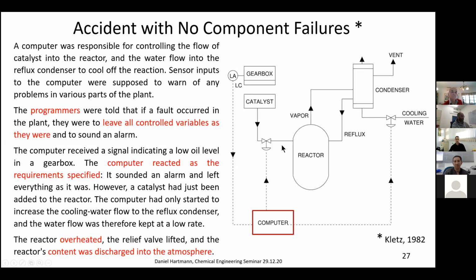And then there was a problem, not related directly to this reactor. The gearbox had not enough oil, but the computer did what the program said it should do. So it sounded an alarm and left everything as it was. It happened that at that time, there was more catalyst in the reactor and very little cooling water, and it was overheated and discharged into the atmosphere and so on.